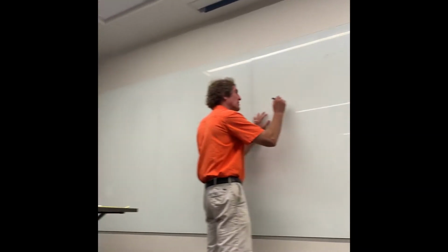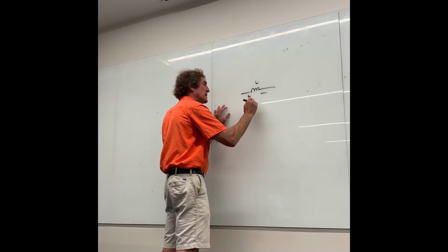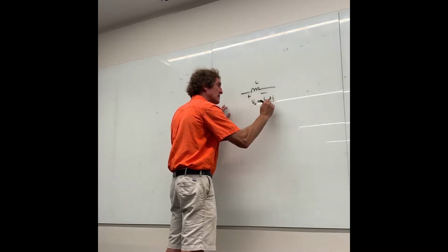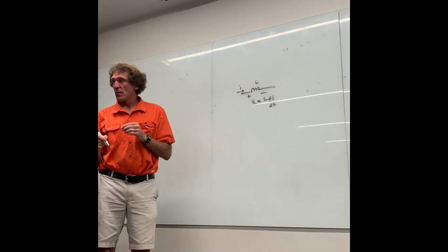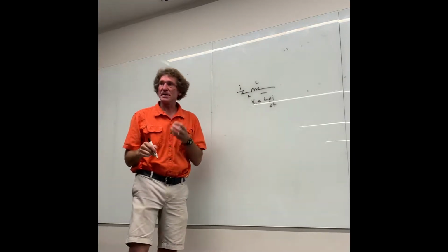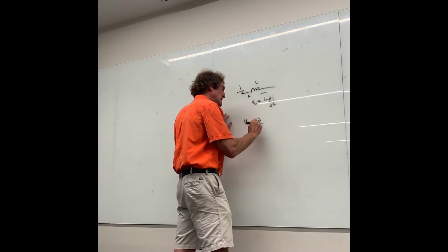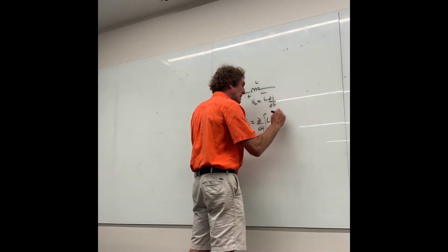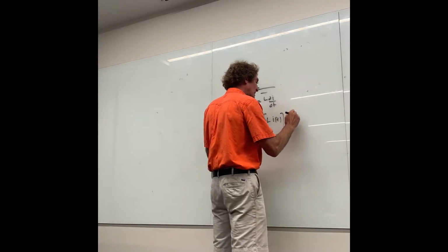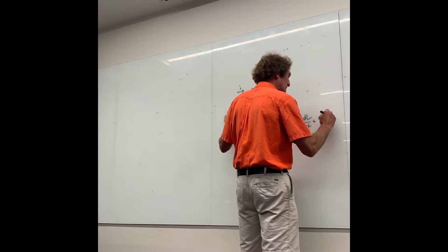Let me explain one other thing. You were taught a long time ago that if you have an inductor L, the voltage across that inductor, V_L, was equal to L di/dt, right? And that would be a current I going into it. Do y'all remember that? Well, that's partially true. That's true if the inductance doesn't vary with time. But if it did, V_L would actually be equal to d/dt of the quantity L times I of t, which would be equal to I of t times dL/dt plus L times di/dt.